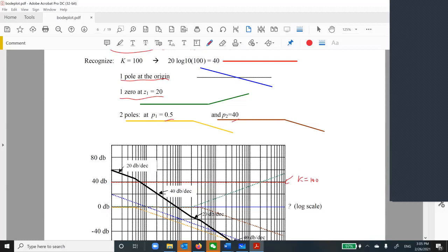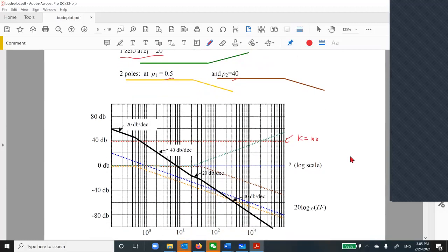All right. So then we need to check the x-axis in here. So where is the 1? So this is 1, okay? This is 10. This is 100. This is 1,000. So for the 1, I know that this blue curve, from 1 here, you have a decade in here, this is 0.1. So you have a decade in here, so this is 20 dB. So the slope is 20 dB. So this one is 1/s, okay, 1/s.